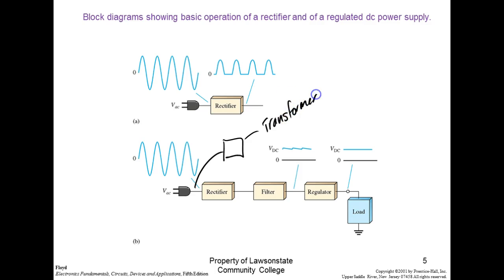I'm not saying you won't find linear power supplies without transformers, but probably over 90% of them have a transformer. And what can we do with the transformer? What's the function of the transformer? Step up or step down, but in power supplies, it's to set the voltage to the load. So if I'm going to have a power supply, that transformer is going to establish the voltage that I take from AC and convert to DC. And so sizing that is very, very important.